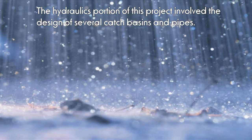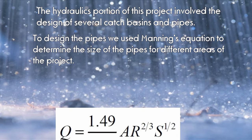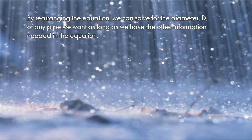The hydraulics portion of this project involved the design of several catch basins and pipes. To design the pipes, we used Manning's equation to determine the size of the pipes for different areas of the project. By rearranging the equation, we can solve for the diameter of any pipe we want as long as we have the other information needed in the equation.